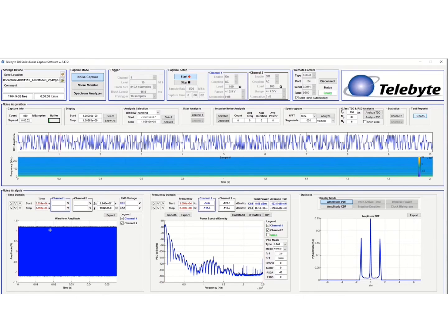Okay, so we have our signal up here. The first thing to notice is it does look like it's a 2.4 volt peak-to-peak operating mode, because I see voltages above +1 and -1 volts. And we can zoom in now to look at the signal.